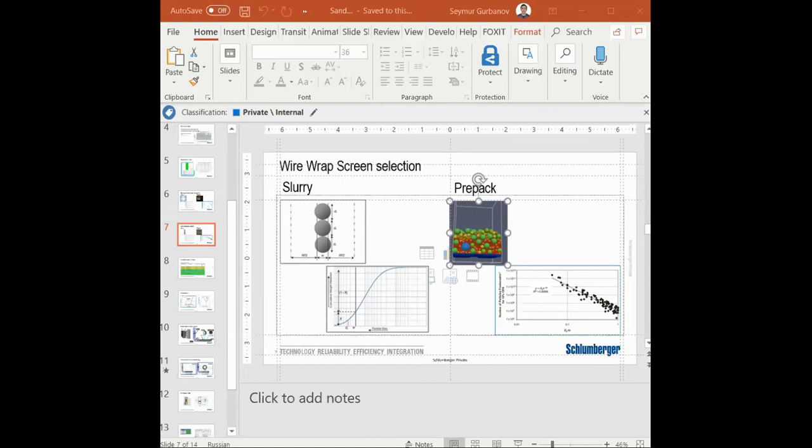So the best way to control that erosion is to avoid the sand production altogether, or minimize it. That's the best, because you couldn't live with the sand producing. That's not the way. Even if you manage the sand erosion, and somehow dispose of the excess sand on the surface, in the wellbore you're losing your solids. So you're losing your formation and you're generating cavities.